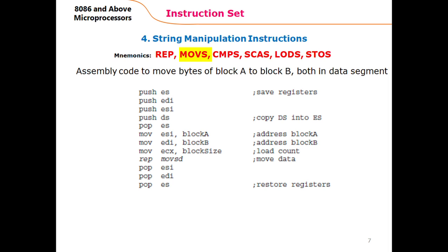So to make this kind of transfer happen, we have to copy the value of the data segment register to the extra segment register, and then the microprocessor would assume that the transfer is happening just like normal from the data segment to the extra segment, but the extra segment would now point to the data segment instead. And it is important to store or save the content of the extra segment for later use so that it can point to the real extra segment again.